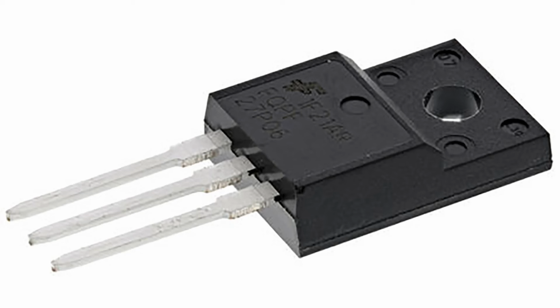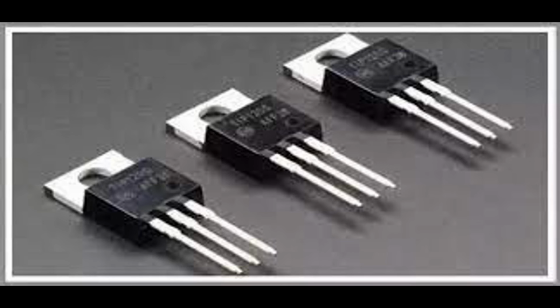9. Versatility. Description: Power MOSFETs can be used in various configurations, e.g., parallel or in series, and are compatible with a wide range of topologies, e.g., half-bridge, full-bridge. Advantage: Their versatility makes them suitable for diverse applications, from power supplies to motor drives and renewable energy systems. 10. Low noise operation. Description: The operation of power MOSFETs produces minimal electromagnetic interference, EMI, and switching noise. Advantage: This characteristic is crucial in sensitive applications, such as audio amplifiers and communication devices, where noise can degrade performance.